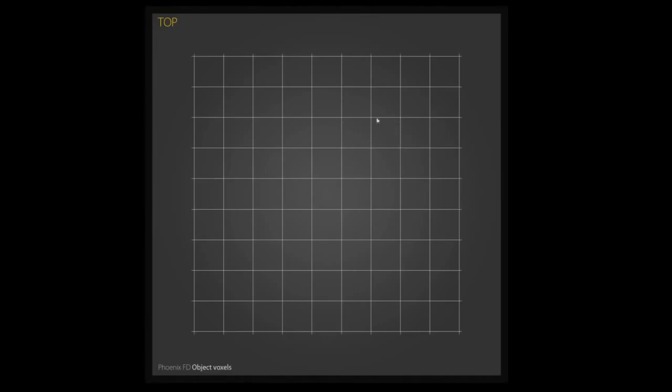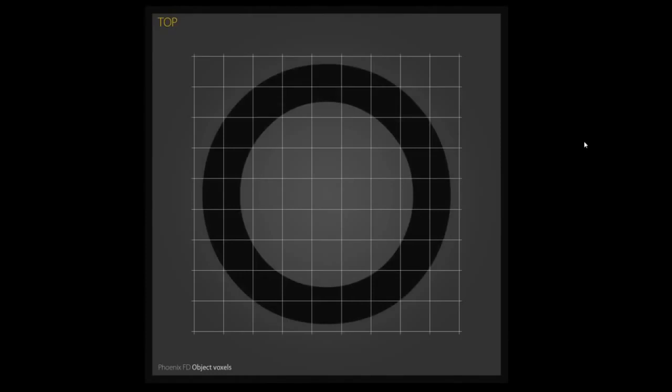And what we've done so far is we've created an object, and then we created a source, and we started filling this with liquid. And what you can see in this image is that all of the voxels that are intersecting the geometry, like this one, are left empty. There is no liquid inside of them. So that is exactly what the circumscribed mode does. It considers the intersecting voxels as solid, so no liquid can go inside of those voxels.